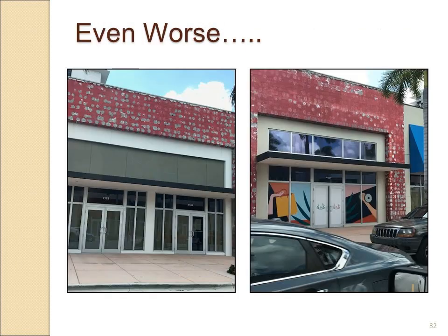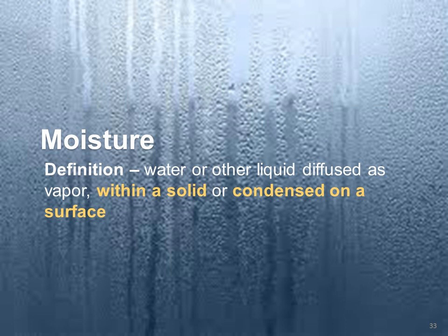And we see it's even worse when you install over a membrane and you have that type of practice. When moisture gets to it, you see in the top right there's a little palm tree. It'll show you that's South Florida. And in those areas, you'll see that the moisture gets to the mortar, things expand and contract, expand and contract due to moisture and thermal changes. And the next thing you know, you have tile falling off the building.